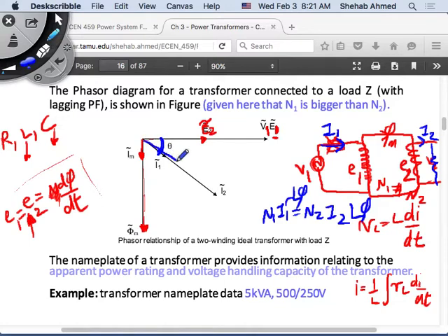So then this is where I've put my load, and since I step down the voltage on the secondary, and I have a certain current, that means I will step down the current on the primary, and the voltage will be higher, right? So everybody's okay with the phasor diagram, to a certain extent? Okay.